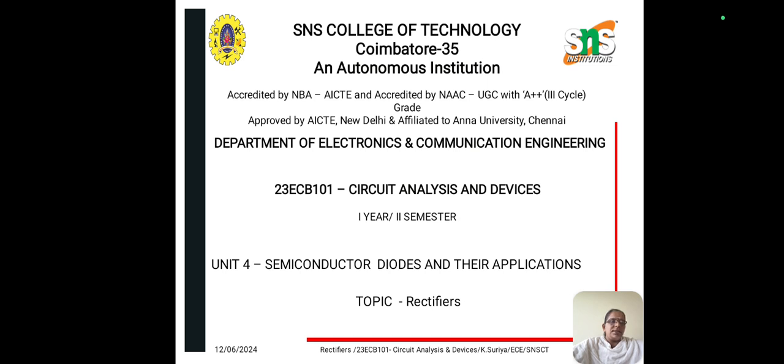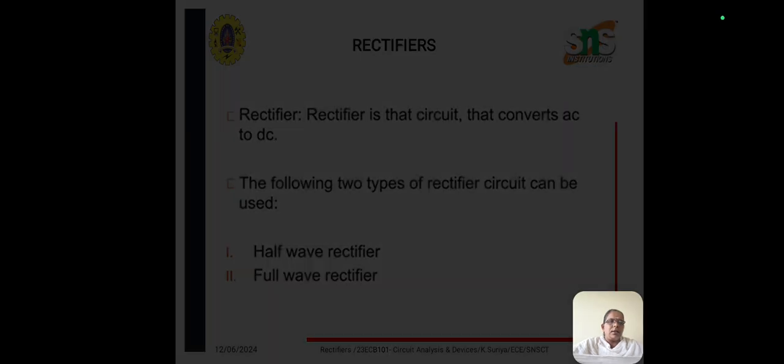In this video, let us see about rectifiers and its types. So, a rectifier is an electronic component that converts alternating current into direct current, ensuring a unidirectional flow of electric charge. As we know, electricity reaches our homes from power grids in the form of AC, but most commonly used electric appliances such as mobile phones, computers, televisions, fridges, etc. operate on DC current. Therefore, the rectifier becomes a very useful component in electronics.